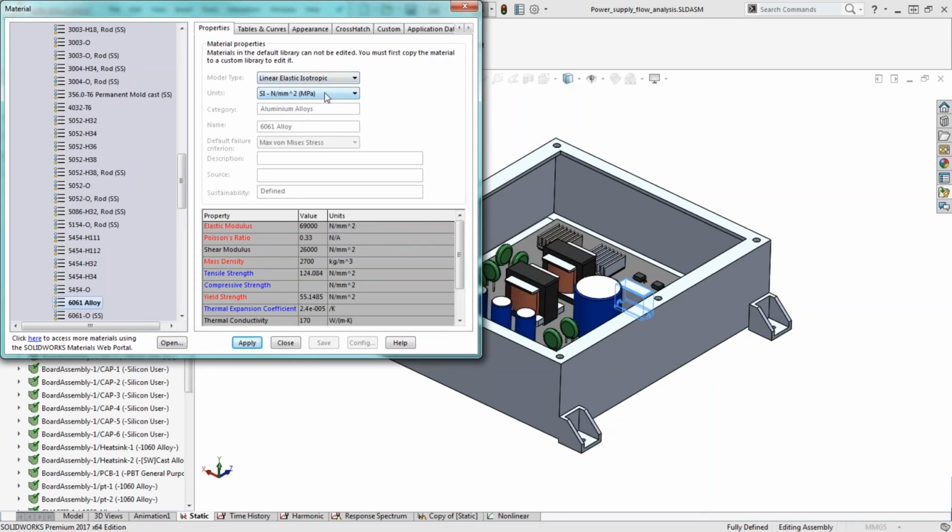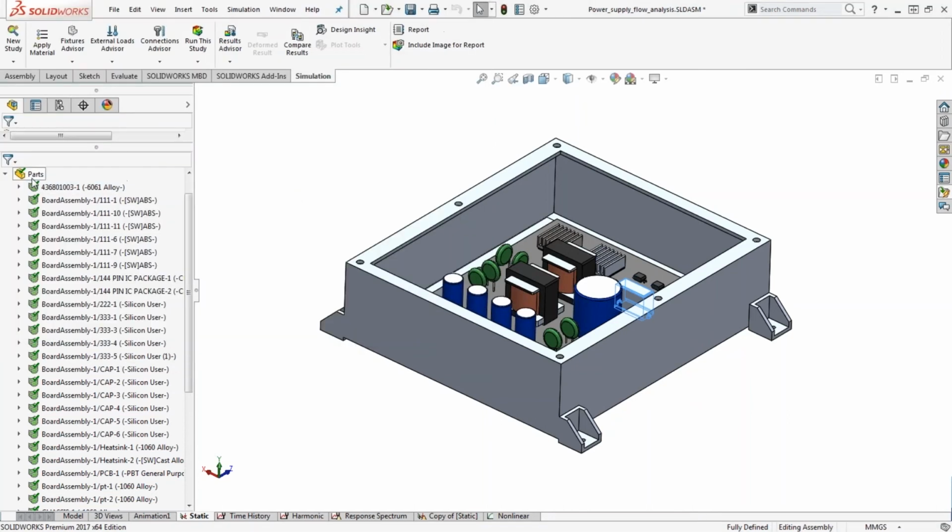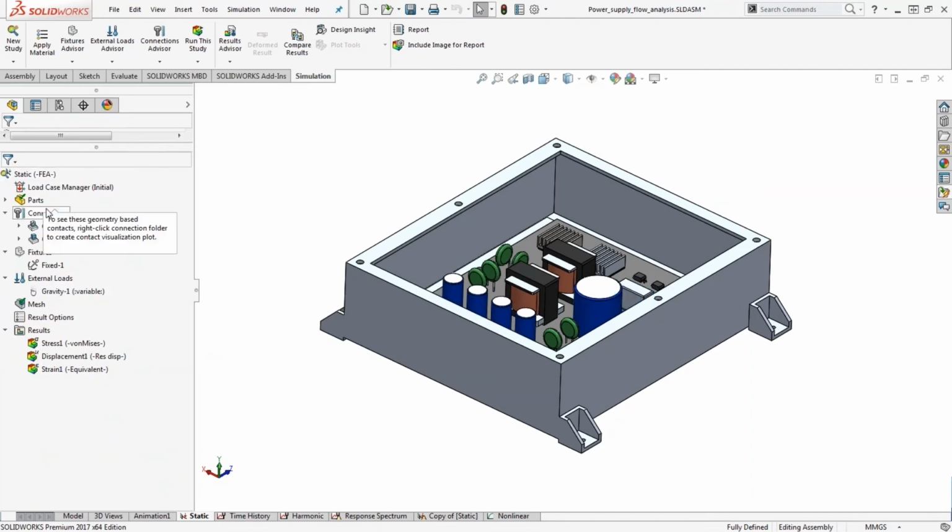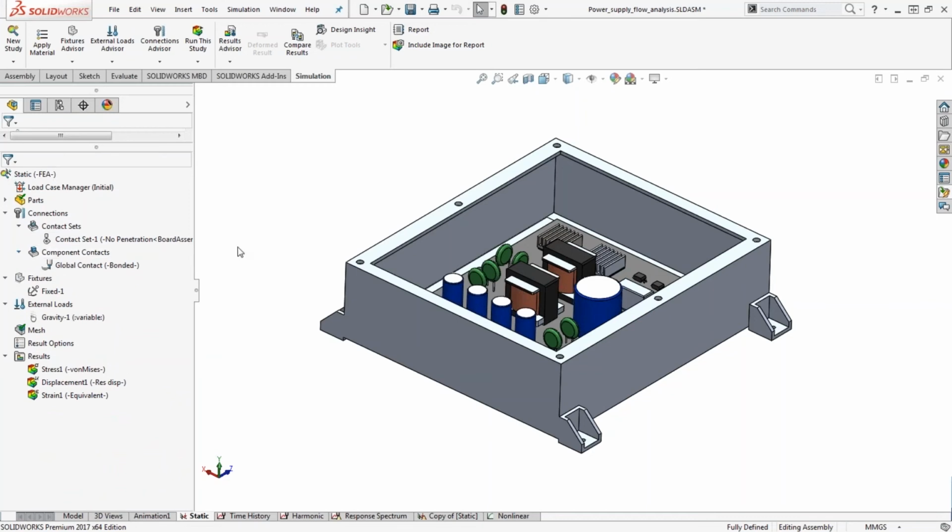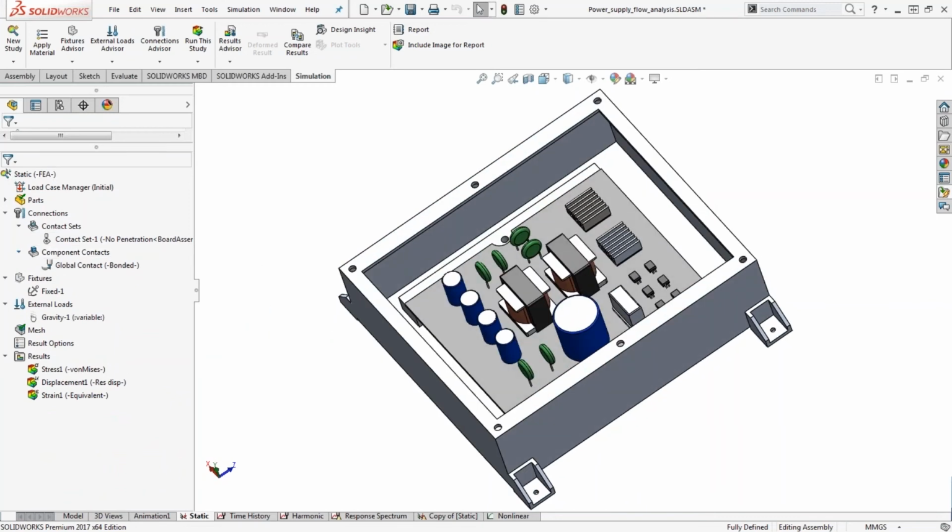We also assume that the loads are applied slowly and gradually, meaning that we can't apply any fast or shock type of loading within Simulation Standard or within our linear static. So the inputs that we apply are, of course, some sort of linear material definition, and then some sort of restraint and some sort of load, gravity, or prescribed displacement to actually deform the model. And the results that we get are, of course, stress, displacement, strain, and factor of safety.